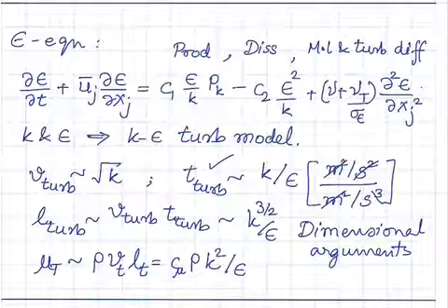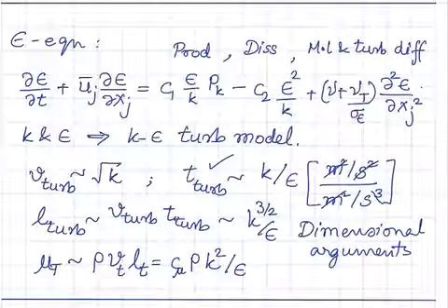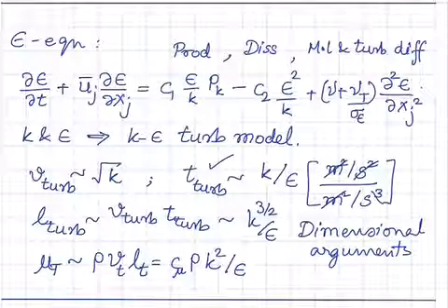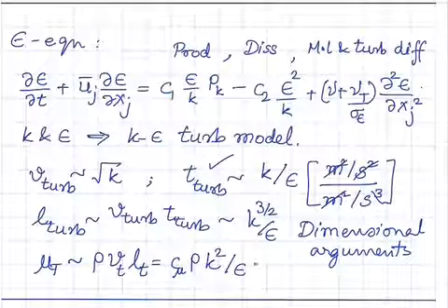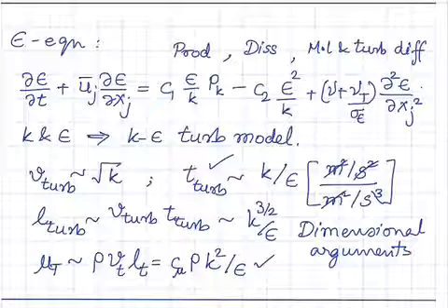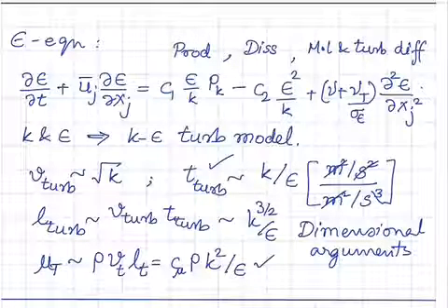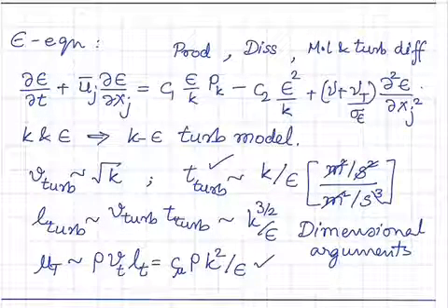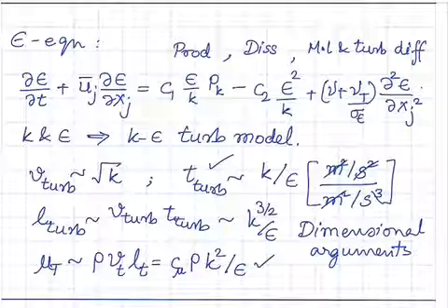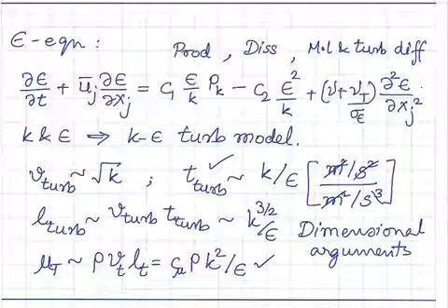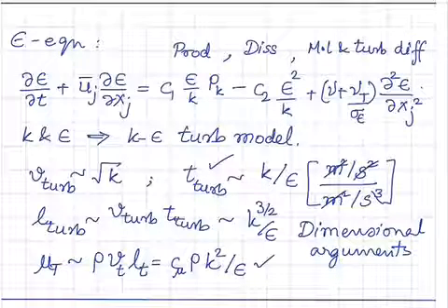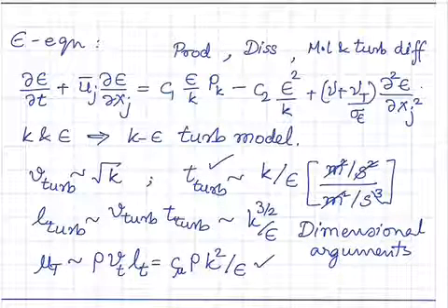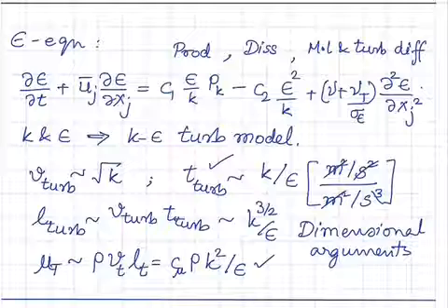So in a k epsilon turbulence model, we solve equations for k and epsilon which are of this kind. We get k and epsilon at every point, with which we now define the eddy viscosity at every point in the flow. And that eddy viscosity formula closes the set of equations, so we can actually compute all these variables without any unknown or unclosed term.